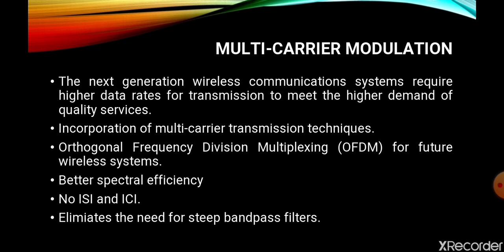Later on, with the development of the IDFT and DFT, that is discrete Fourier transform techniques, and employing those techniques in OFDM, it was possible to eliminate the use of subcarrier oscillators at the transmitter and the receiver. The availability of fast DFT algorithms, which is nothing but the FFT, fast Fourier transform, significantly reduced the implementation complexity of OFDM modems. Further studies and development led to the advancement in the integration of such technology, making it much more cost effective.